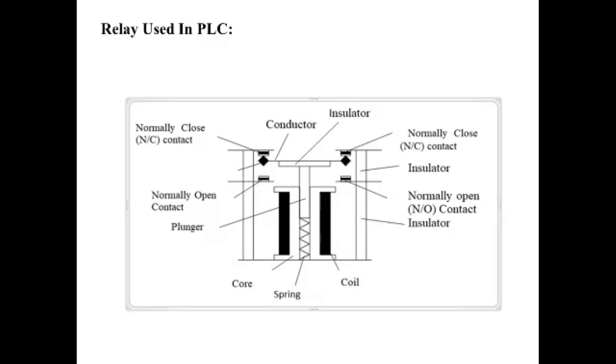If the power is applied to the coil and switched off before the preset time is reached, the relay contacts are never activated. These delay-on relays are useful for delaying the turn-on event. For example, when a motor is started on a machine, a TON time delay relay can be used to disable all the other controls for a few seconds until the motor has time to achieve its running speed.